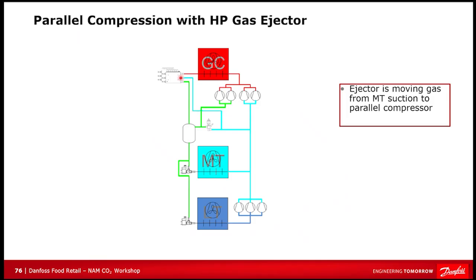When pressures are high enough coming out of the gas cooler, that's where we're able to kind of siphon in refrigerant on the CO₂ line from the suction coming in here. And by doing that, however much flow we are able to bring in based on how high the pressure is at the gas cooler, that's all refrigerant we're able to take off of the medium temp compressors and reduce some of the energy consumption and compressor usage in general there. So those two lines make up your inlet flow into the ejector, and then our bottom green line is your flow out to the receiver.